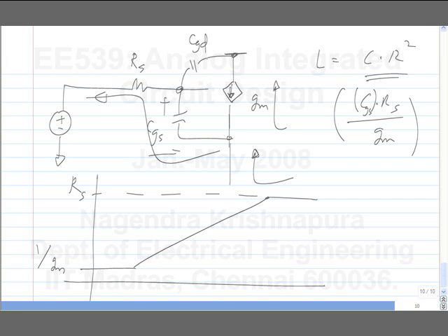When analyzing circuits like this, you have to assume that there are distinct ranges of frequencies where one or the other component is significant. Now, that may not be true in practice. It may not happen that way. Then you evaluate it and see if it's true or not. So, let's assume that Cgd is smaller than Cgs, which is quite reasonable. We can assume that it is quite a bit smaller. What happens to the impedance at very high frequencies?